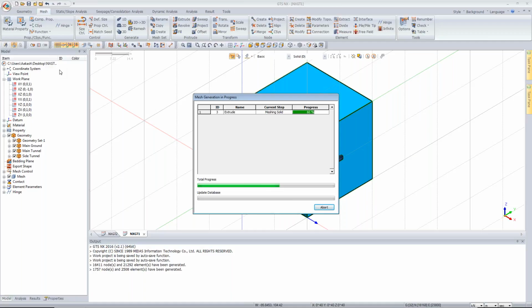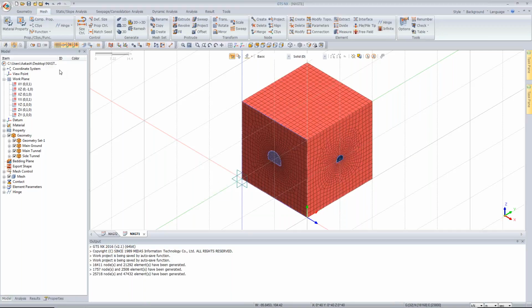You might be thinking that you are deactivating excavation 1, but you might be deactivating excavation 7, and activating the reinforcement for shotcrete 1. As a result, it can lead to numerical instability, and at times create a lot of confusion: even for such a stable soil, how exactly are we not able to converge the model? So one should take care of that.